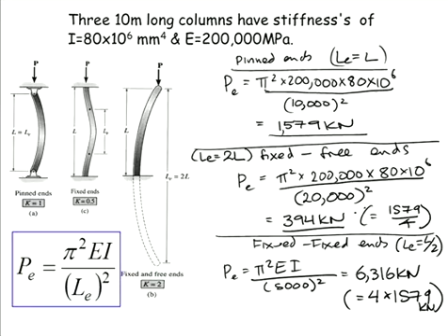Now when you come and do your project, if you are designing a single span bridge, you are not going to assume it's supported by the surrounding buildings. You're going to have columns there. Because those columns are so close to the building, we can actually tie them horizontally into the building and assume the top of the column isn't free to move. Okay? So if you just have those columns to design, assume it's pin-pinned.